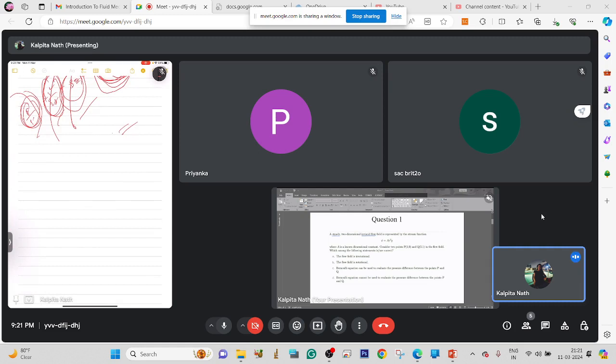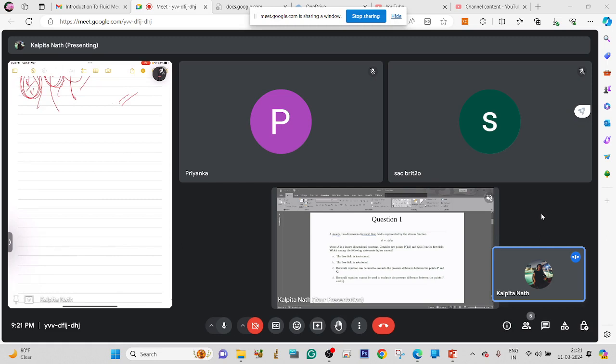So yeah, now, first of all, as Priyanka has already done, and also Brito has also done, we'll check the rotationality of the flow. So i j k, del x, del y, del z, u v w. We have also done this in the previous week, right? So this is del v del x minus del u del y. So this is minus 2ay. That means this is not equal to 0. That means the flow is rotational.